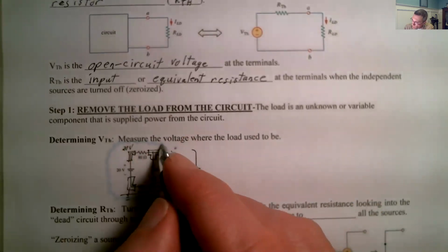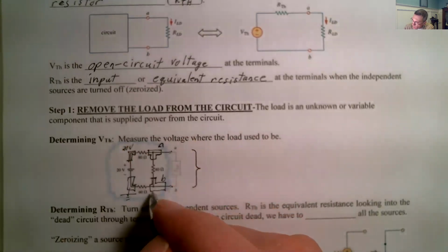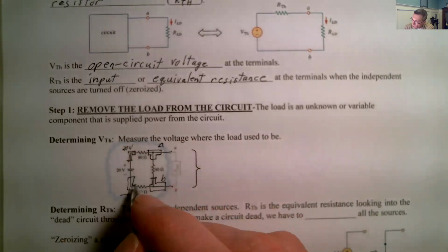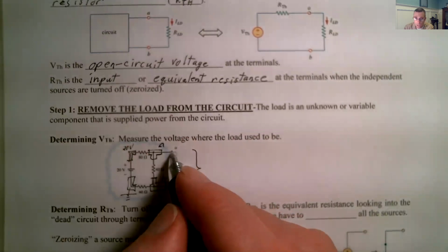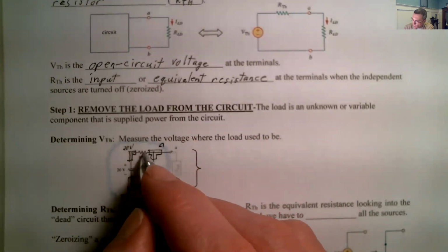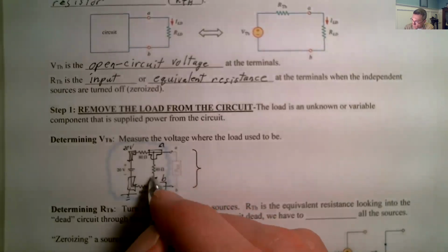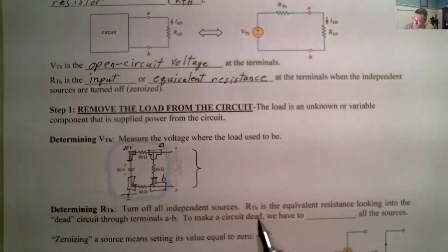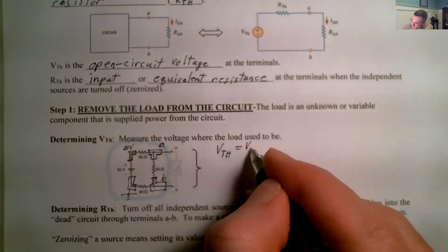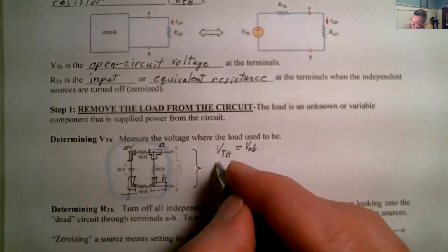Now what we're trying to do is find the voltage between A and B. And between A and B is this 40 ohm resistor. Now, if this is an open circuit, there's no current flowing that way, right? So if there's no current flowing that way, that means that all the current flowing here goes through there, which means that these two components are in series. So this is all one big series circuit. If that's a series circuit, and we say VTH is equal to VAB,